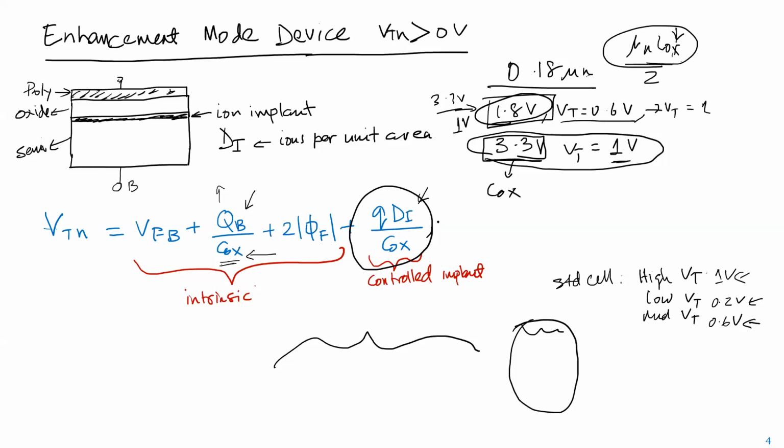Sir, like I said, maybe my understanding is not correct till now. My understanding was that by changing the COX, I can change the VT, and I never thought that it is going to change the VDD also. I thought VDD is going to be the same, and if I just change the TOX or somehow change the dielectric constant between the poly and the substrate, that is again going to change the COX and that will change the VT.